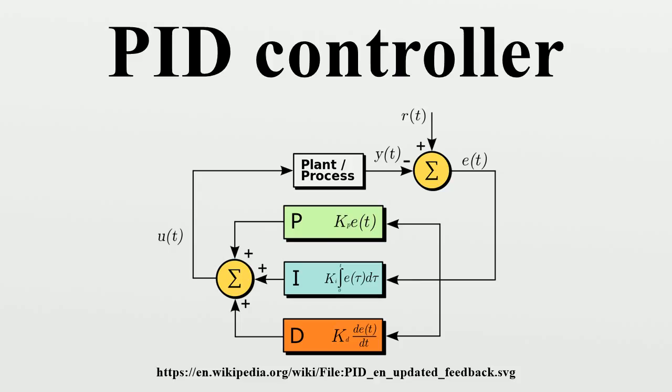Stability. If the PID controller parameters are chosen incorrectly, the controlled process input can be unstable, i.e., its output diverges, with or without oscillation, and is limited only by saturation or mechanical breakage. Instability is caused by excess gain, particularly in the presence of significant lag.